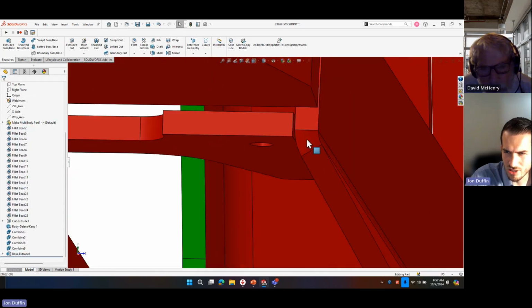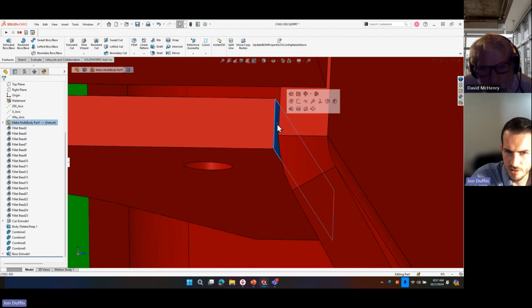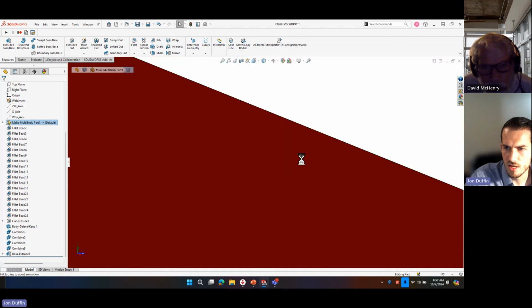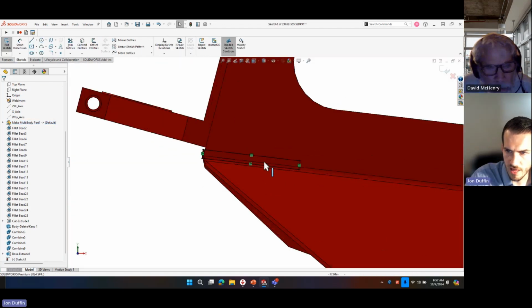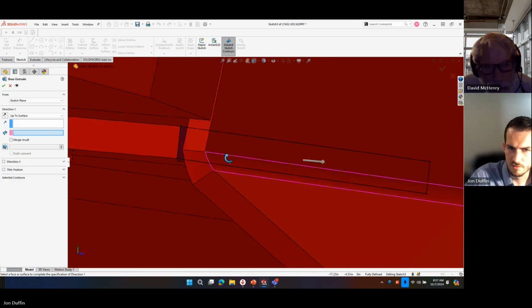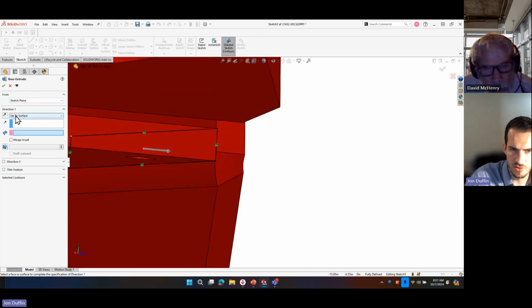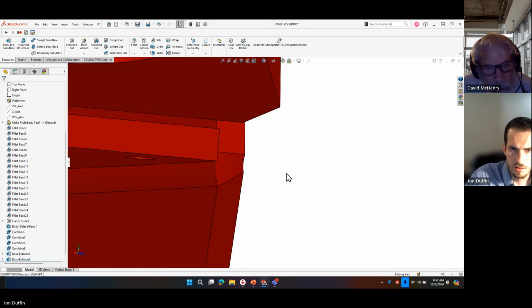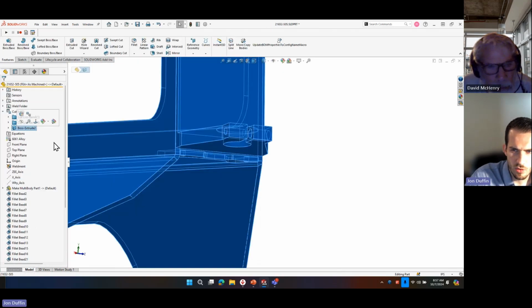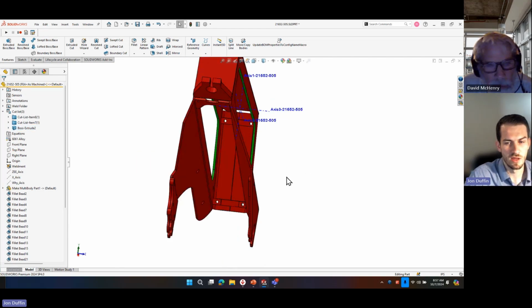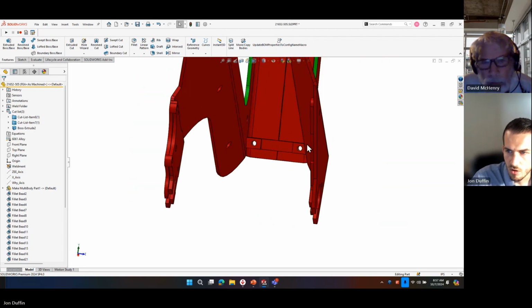Okay, so that combined it. And just for the sake of our structural rigidity, we'll want to do the same thing over on this side here. So hey, we'll go into the sketch. I'll convert that, hit my C key, my shortcut, and then I'll extrude this up to that surface. So up to surface, up to this one on here, and I'll have it merge so it's all one body at this point. Okay, so now we are down to this part and these two. So we're down to 3 parts, and pretty soon it'll be one single part once we get it there.